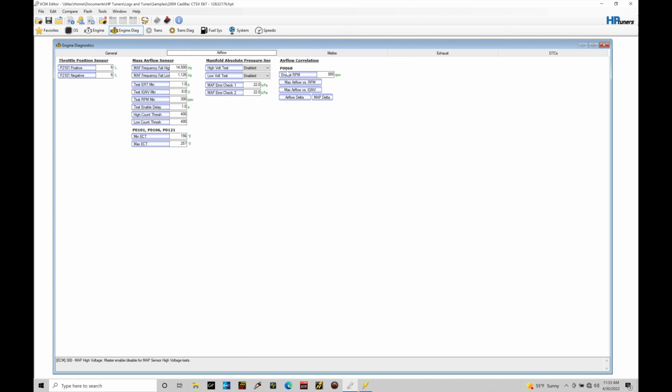So when you're doing your initial calibration, you want to go in and set this and turn this off essentially, and I've demonstrated that. We'd set this something high, something like 8,000 RPM. This would turn off the checksum for the P0068. So you shouldn't get any throttle shutdown or any kind of odd problems going into limp mode if you have your enable RPM set very high here. But once you've done your calibration, you've dialed in your airflow model, once everything is sorted out with the vehicle and it's running properly, that's where we're going to take a look at some of these tables here to dial in. So let me return this back to 800 RPM.